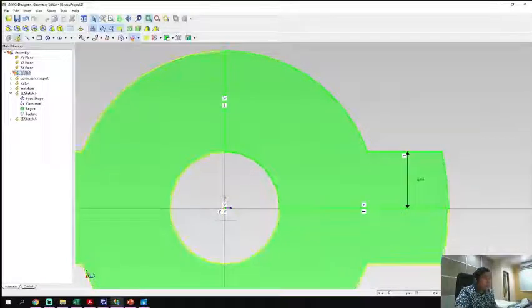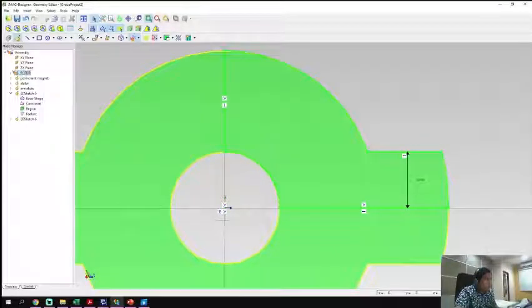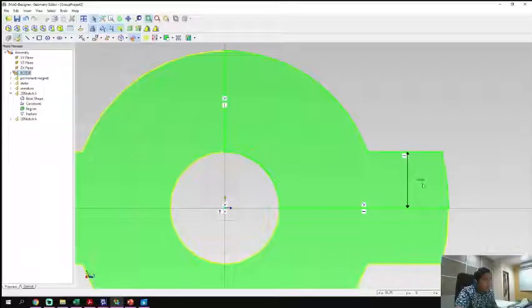And then for the first half of the circle, we trim the below part, and we make a line. As you can see here, this has the line. Then we trim it, and this part, the upper part between 60 and 51.25, we delete. As you can see here, we get a tunnel, and we make it 12.5 because our calculation is 12.5 for the tunnel here.